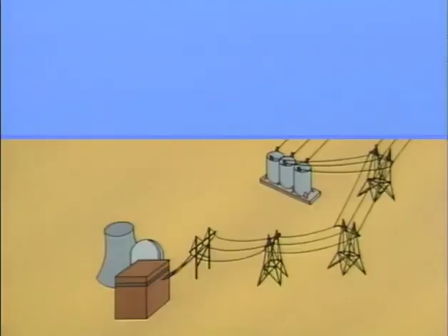Transmission systems are not specifically designed to prevent resonance, but it's unusual to find a system in which inductive reactance and capacitive reactance actually are designed to have the same value. More common are systems like the 25-mile transmission line we've been using as an example in this program. In that system, we calculated inductive reactance and capacitive reactance that have different values. Let's see how inductive reactance, capacitive reactance, and resistance combine to make up the total impedance of that system.